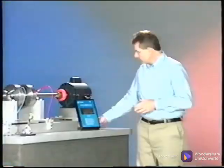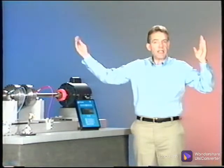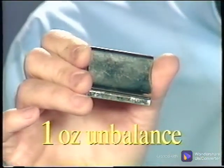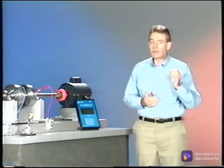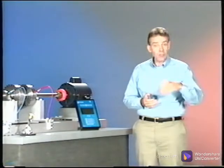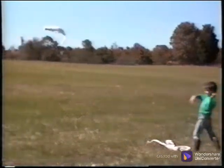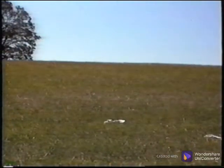One is the effect on an unbalanced amount due to centrifugal force and changes in speed. For example, a 44-inch diameter fan is turning at a speed of 2,220 RPM and has 1 ounce of unbalance on the rim of the fan. The effect due to centrifugal force is similar to the force on a ball in a stocking as it is swung in a circle. The force pulls out on the stocking, causing it to fly away from the center of rotation. If the stocking is swung faster, the force pulling it away from the center of rotation increases dramatically.